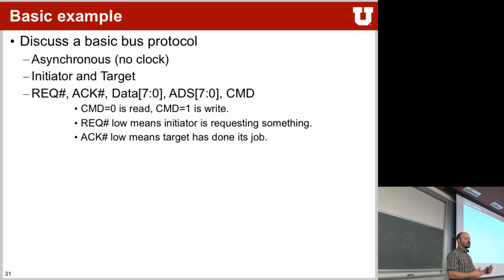So let's just assume we have an address, right? And then you also have some data that must go over that bus. You can imagine a bus as a bunch of wires that go from one place to another. Some of them are bidirectional. So these are lines that everybody can write. You have to make sure that not two people try to write them at the same time.